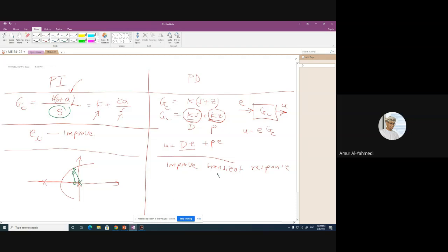But for the PD controller, you have, again, let's say a pole here and a pole there, and let's say my root locus will be something like this. I want to change it now, such that my root locus will pass through this point. By adding a zero somewhere here, my root locus will be different. So this will go, let's say, to there, and the other pole will pass through this point.